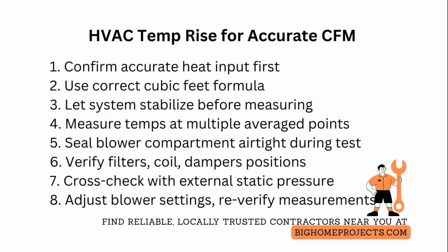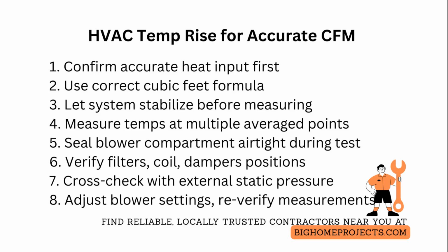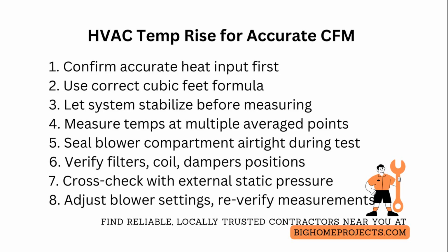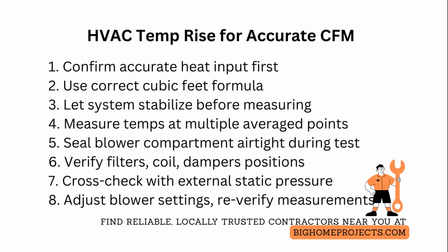Verify filter condition, coil cleanliness, and that all supply and return dampers are set as during normal operation, because changes in external static pressure directly change airflow. Record total external static pressure with a manometer and compare to the blower performance table to cross-check your formula-based cubic feet per minute. They should be in the same ballpark.